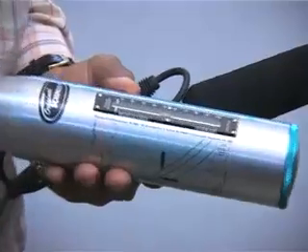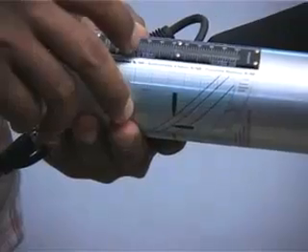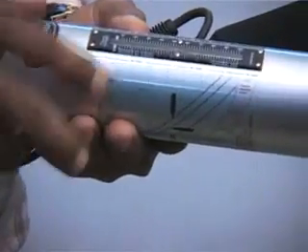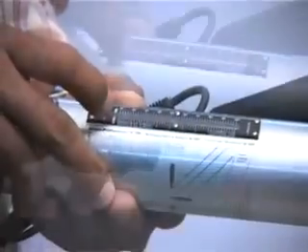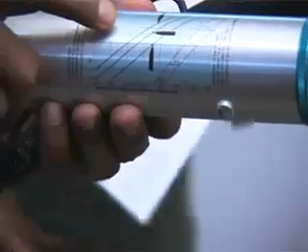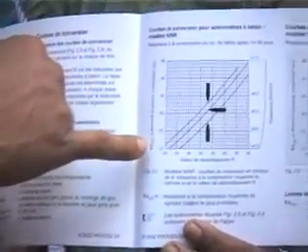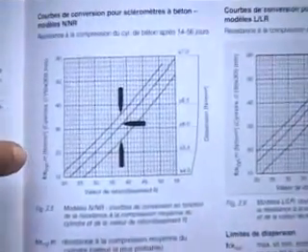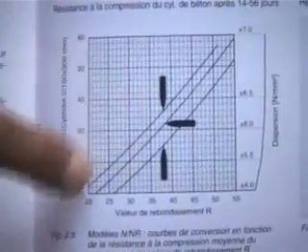particular scale here. We did the testing on the floor, so the rebound index here is 52. The value is 52, and then this value gets converted from a standard chart, which is also given by the manufacturer. You have to read off the value of the UCS from looking at the appropriate curve.